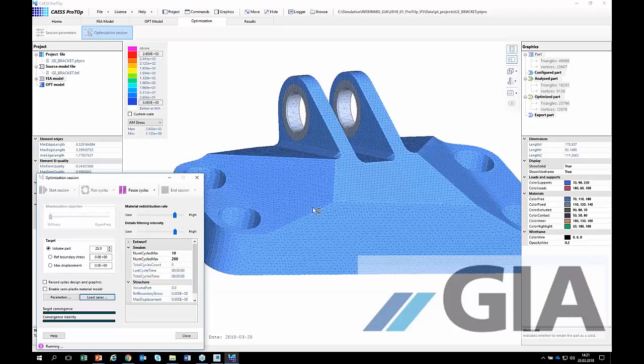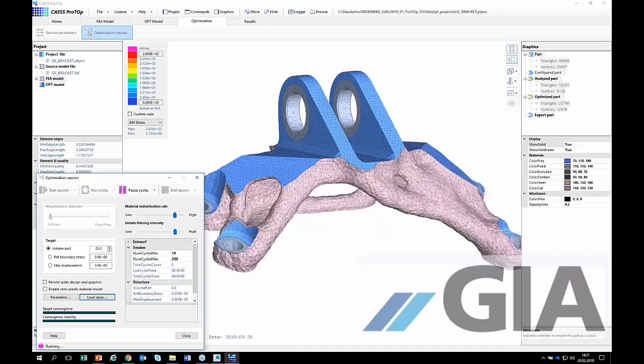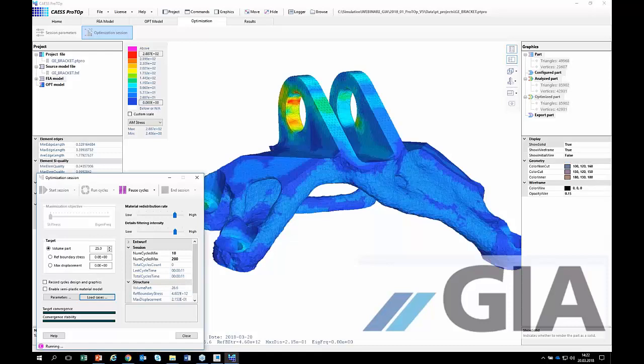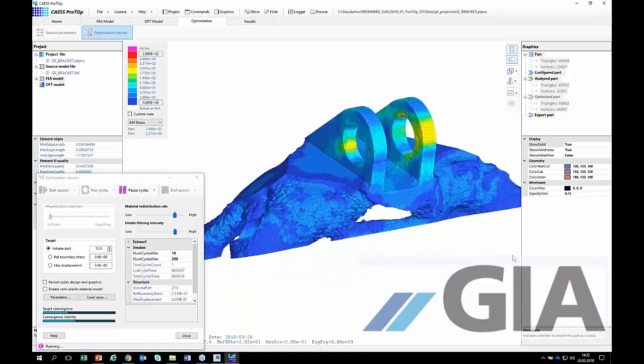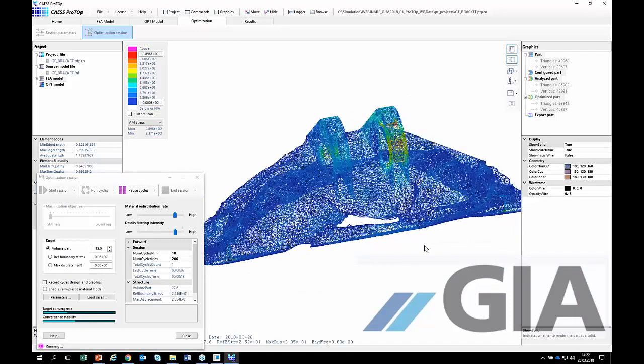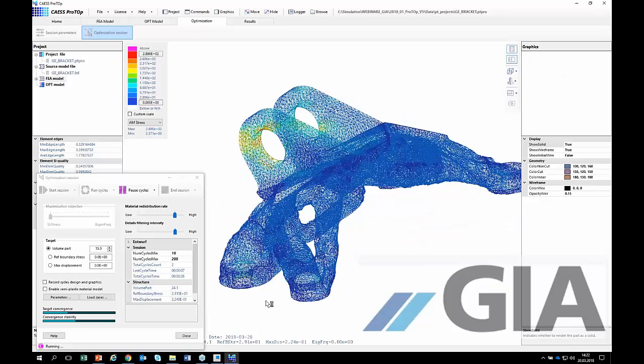So the first step will take maybe 20 seconds, and now we have a much denser mesh, and now with that mesh we really can go close to the limits, maybe down to 15%, and see a very, very interesting organic structure of that component.